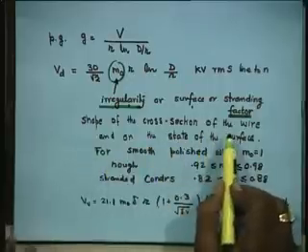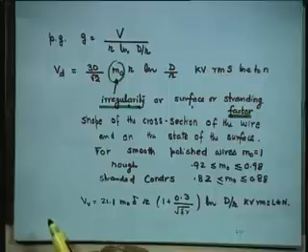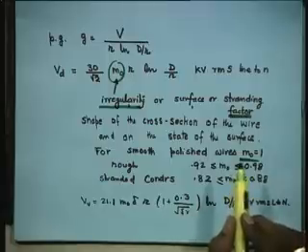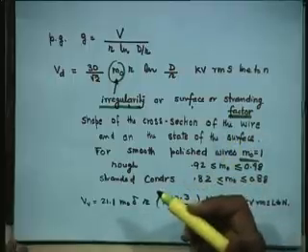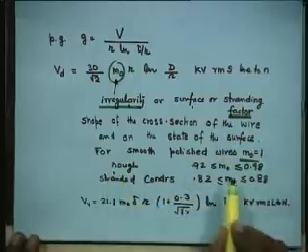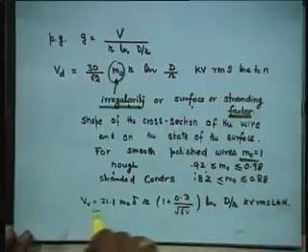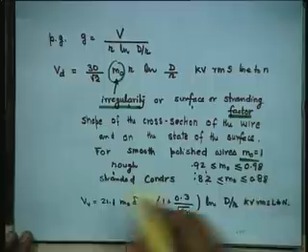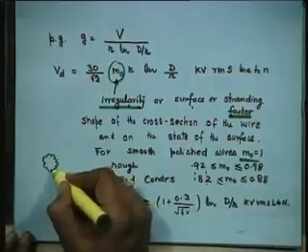It depends on the shape of the cross section of the wire and on the state of the surface. For smooth polished wires, M0 is 1. Chances of corona is minimum if it is smooth. Higher voltage is required. Yes, higher voltage. That is why chances are low. But if it is rough, then M0 varies between 0.92 to 0.98. If it is stranded, then M0 is 0.8 to 0.88. Stranded means like this. It's not smooth.